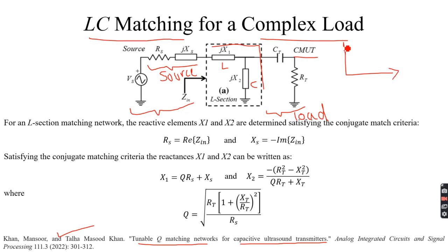Let's say you measure the impedance, and the resistance comes out something like this. It's not that great, but anyway, this is the resonance frequency. If instead of impedance you are measuring the power response of a transducer, then the frequency at which the maximum power is transmitted to the medium by the transmitter is the resonant frequency, and that's also the operating frequency of the CMUT.